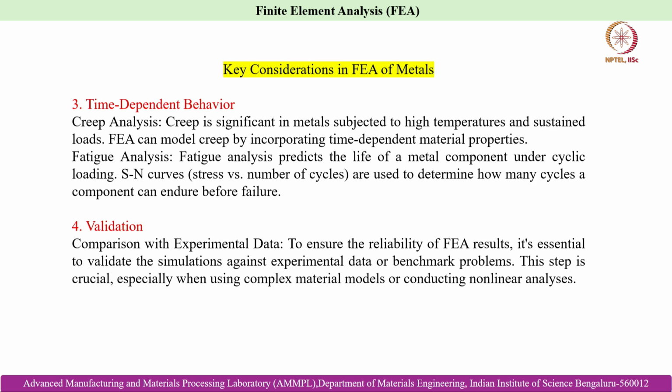Some other considerations are time dependent behavior, like creep analysis, which is significant in metals subjected to high temperatures and sustained loads. FEA can model creep by incorporating time dependent material properties, and it can also be useful for fatigue analysis, where we can predict the fatigue life of a metal component in service experiencing cyclic loading. So, we can predict S-N curves, that is stress versus number of cycles, which are used to determine how many cycles a component can withstand before the final failure.